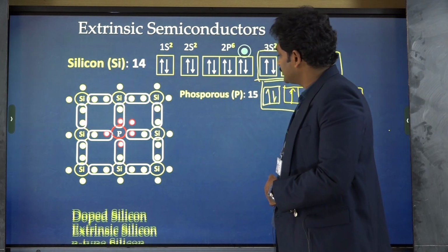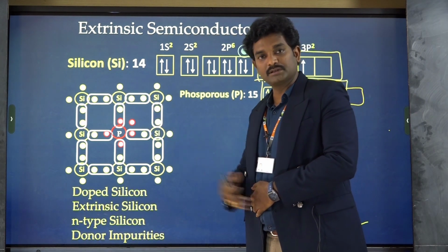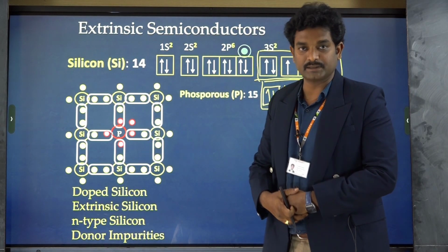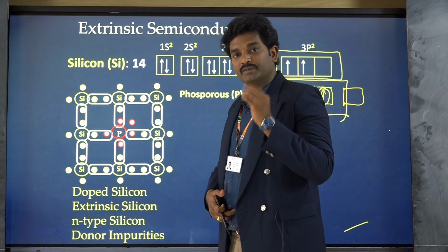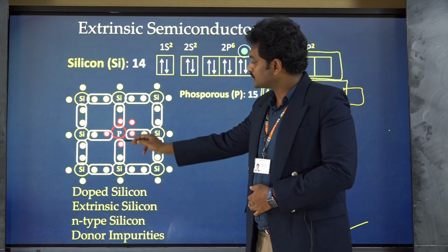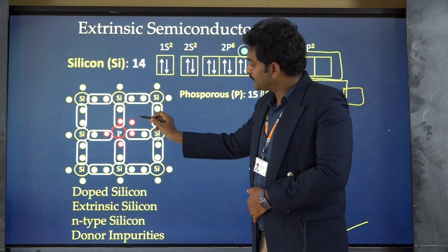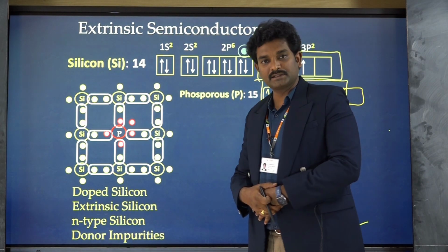So this kind of semiconductors which are doped with impurity atoms like phosphorus, arsenic, these doped semiconductors are called extrinsic semiconductors. Now see here, we have doped it with the pentavalent impurity which is having 5 electrons in its outermost orbit. So 4 electrons have participated in forming bonds with the silicon atoms. There is one extra electron left here. Now this electron charge is minus, which is negative.